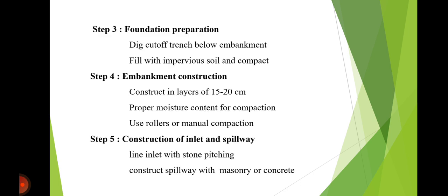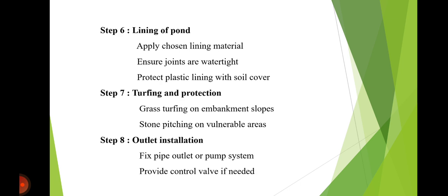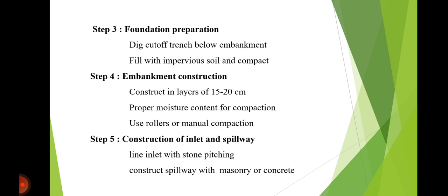Next is foundation and excavation of farm ponds, excavation of the pond basin. Excavate the pond according to the design dimensions and side slopes. Excavation may be carried out manually or using machinery such as excavators and bulldozers.